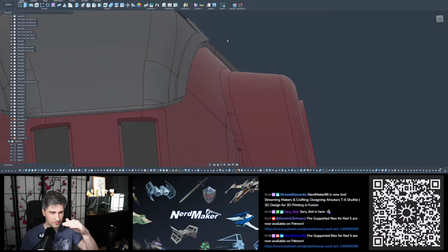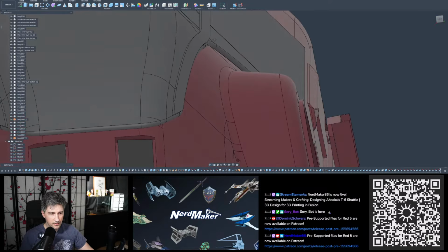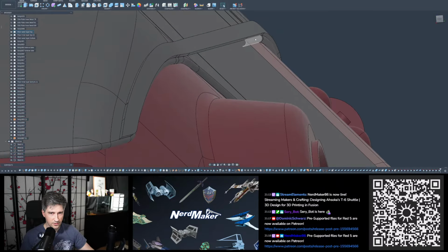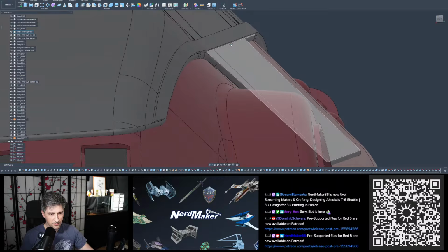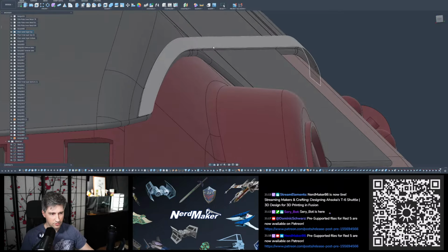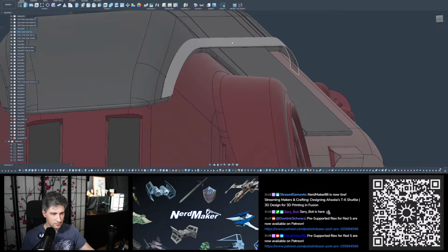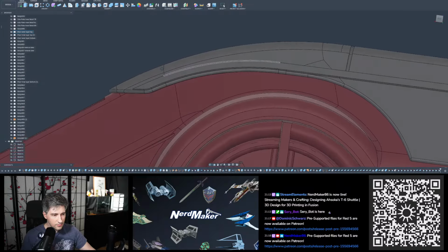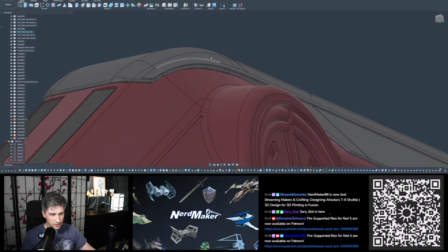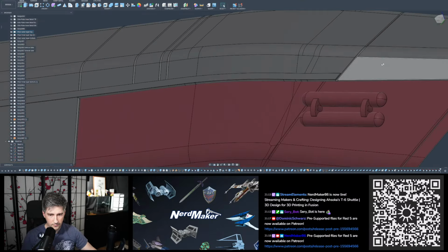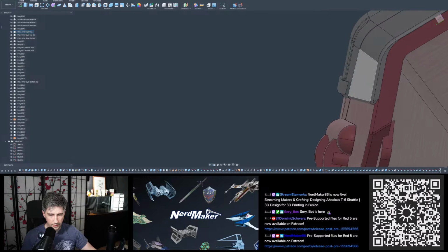Because I extruded it in a horizontal direction basically, and it just didn't look right, so I made it new, made a projection, and then extruded. Well, it's not extruded, it was a face and then thickened up according to the perpendicular to the direction it sits on. And now it looks way nicer.